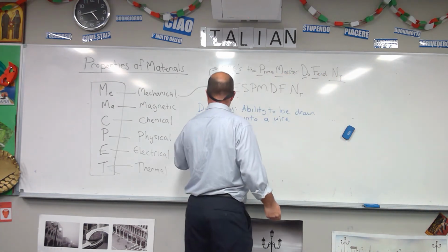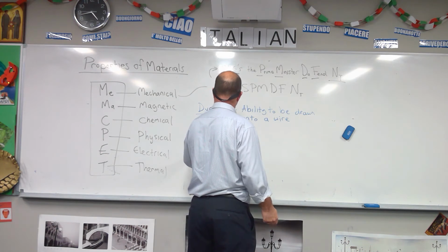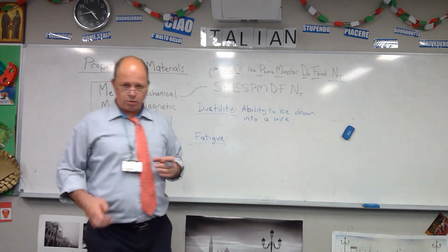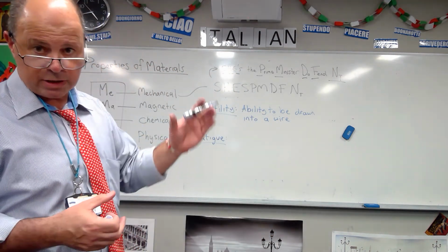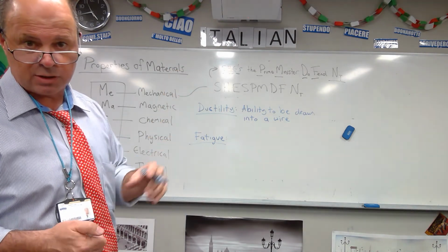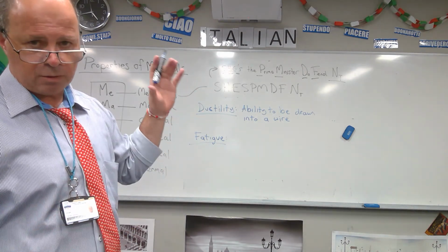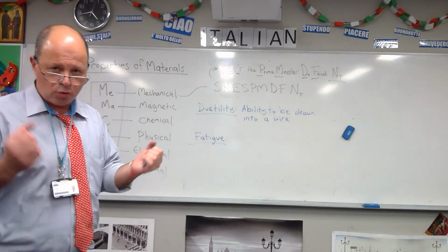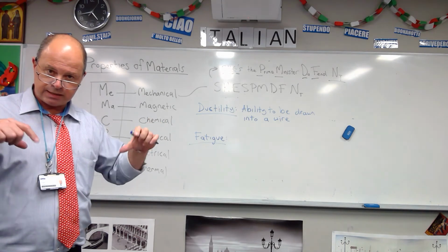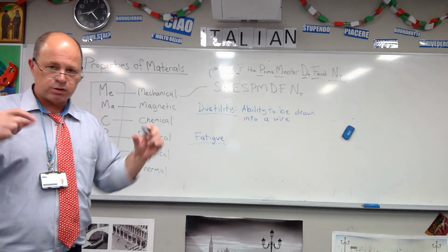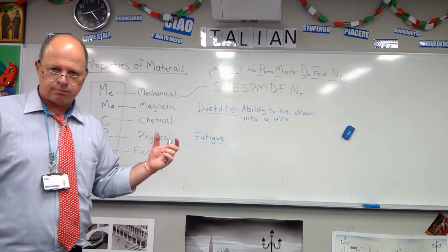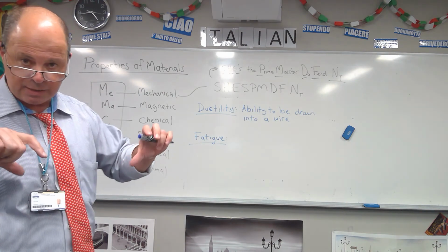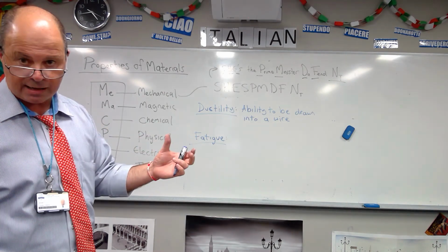Fatigue. Now, later on we're going to talk about loading materials and draw graphs of stress versus strain, all that sort of stuff. It's way further through the course. So all we need to know now is if you're within the elastic limits of a material, we're talking about elasticity, if you stay within those limits, the material always bounces back, okay? And you say, great, no problem at all. Keep loading it, unloading it, loading it, unloading it. And as long as you don't go past that limit, the material won't deform or break.